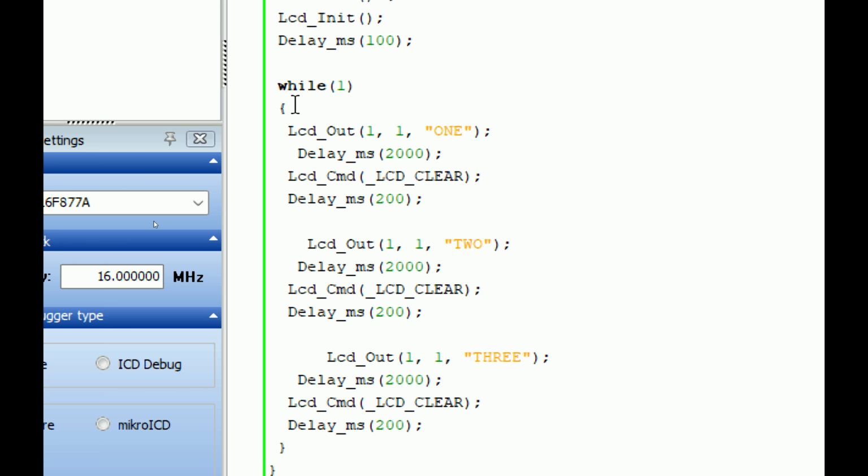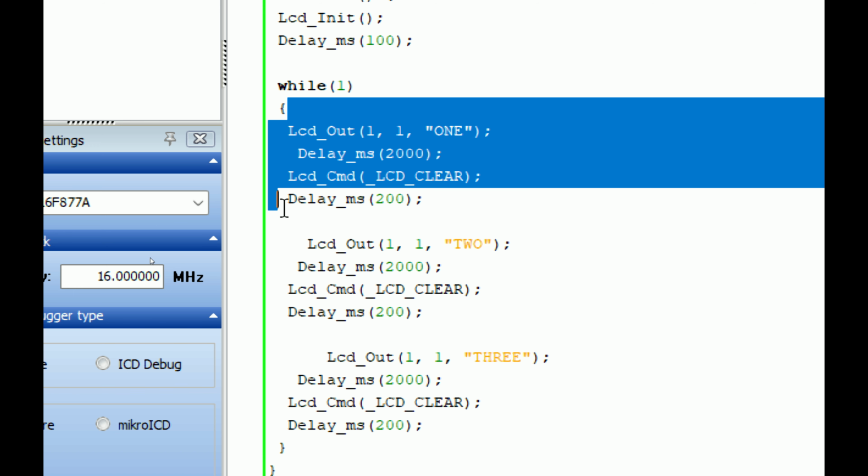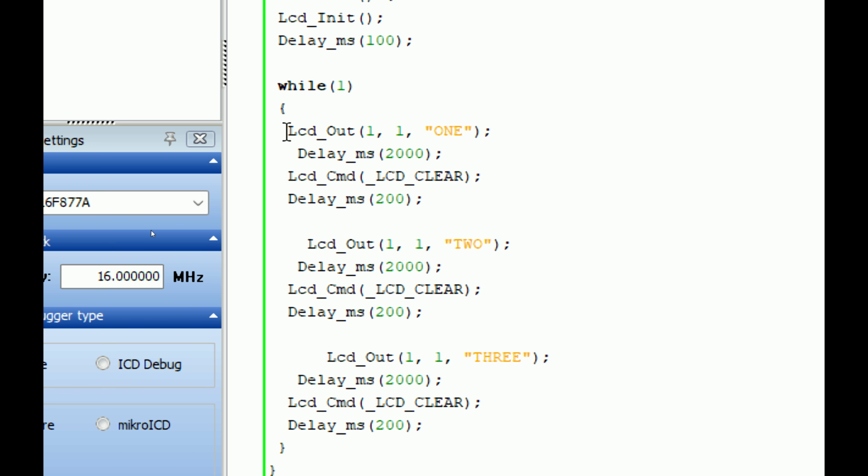Now the goto statement allows you to do jumping and play with your program counter. Your program counter basically is sequential. In case of a microcontroller, it starts executing from 1, 2, 3. It will go sequentially down like this. Now the goto statement allows you to play with the program counter. You can tell the program counter, no, after this statement is executed, go there.